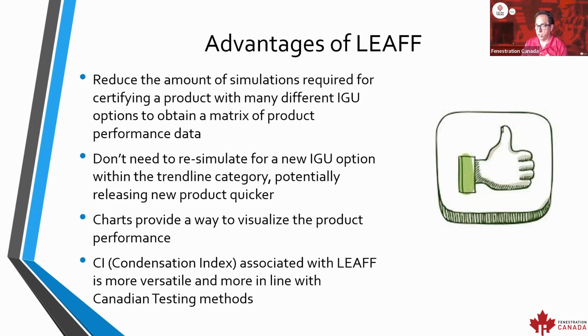So Jag's got another question here. Glazing varies based on surface 2 or 3 low-E, I'm assuming. It's really common to have that variability. Do they need different trend lines? So if you're putting your coating on surface 2 or surface 3, does that generate a different trend line? Nope. They're totally fine, and they're the same trend line. Okay. Another question. Same with gas fill too. As long as the cavity width is the same, you could put air as your highest boundary and then go down to krypton or whatever.